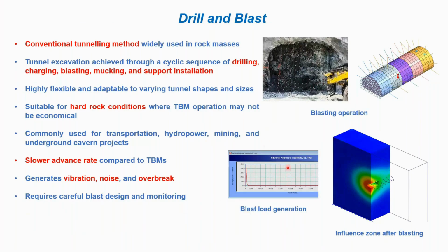So in GTS NX, we can actually create this kind of blast loading. We can generate a blast load for the controlled blasting based on some different approaches given in the literature, like the National Highway Institute US 1991 and some other approaches.